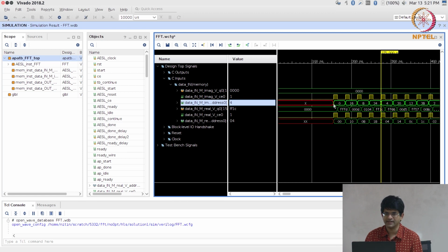That is the bit reversed addressing, because the first block itself is doing bit reversal, right. So effectively what is happening over here is the very first block is doing a bit reversed read, which means that the way it gets implemented is the addresses going out for the very first set of reads are in bit reversed order. So it gets the data back in this format.